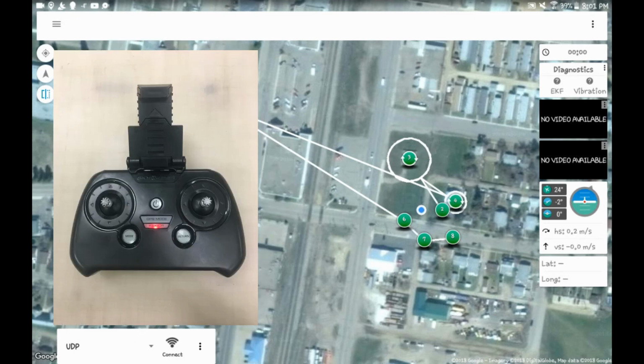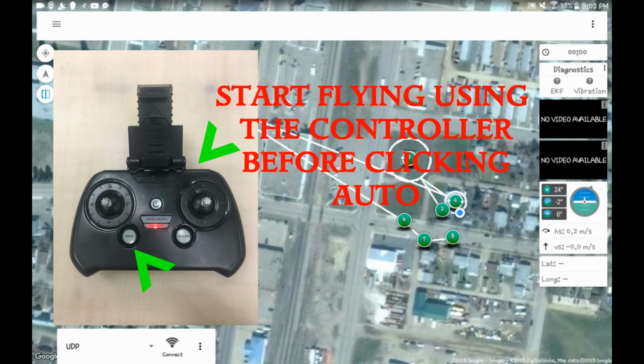So once your drone has the waypoints in it, on your remote control, the mode button, which is the little button below the left joystick that says mode on it, you hold that button down and then you tap the picture taking button. So you take off from the ground remotely, and then you hold down the mode button, tap that button, and away you go on your mission.